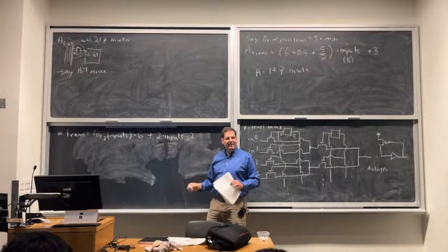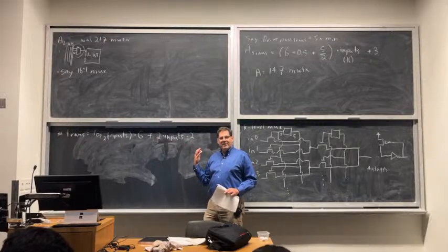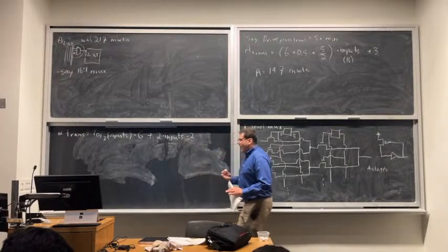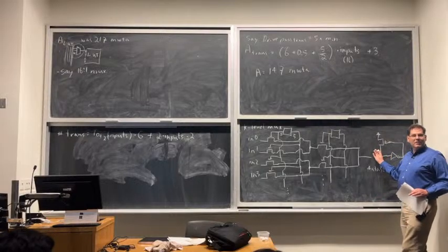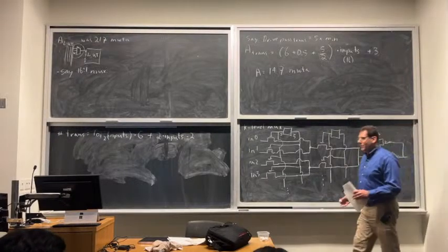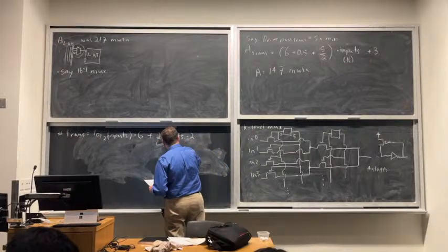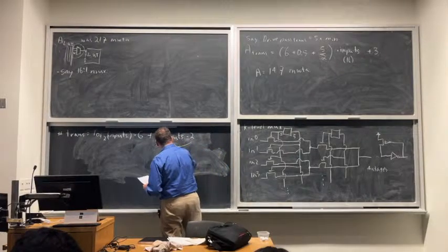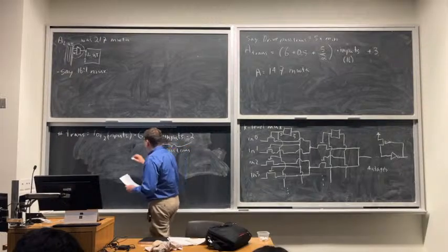If you go add up that geometric series, we could take one more pass gate away because I also get a final one pass gate that's always on, which is not useful, so we just remove that. So we get 2 times the number of inputs minus 2. Okay, and that's the pass transistors. Okay, so this is pass transistors, this was SRAM.